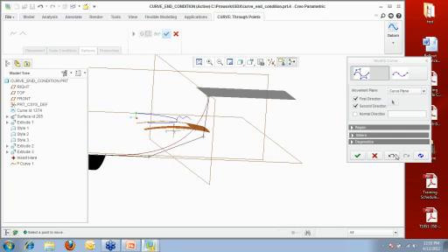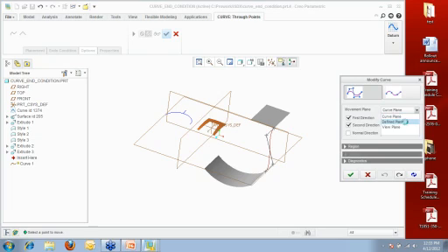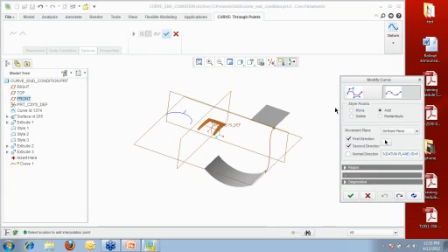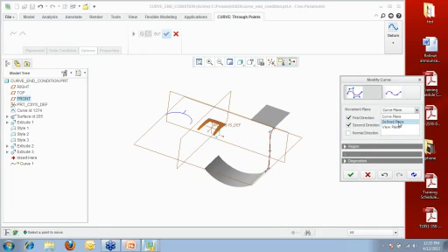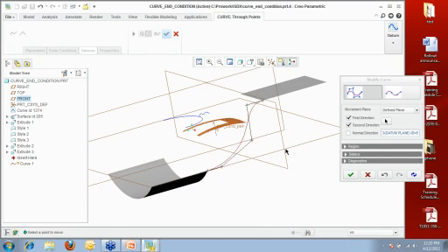The only way that you could really control whether you were or were not moving in certain planes is if you came down into the movement plane and say, I want to define this plane as my movement plane. Let me go ahead and add in a point, make sure my movement plane, let's go back and make sure we pick our defined plane. And now when I drag this curve out, notice how it doesn't dive away from me like it did before. That's really the only way to control that.